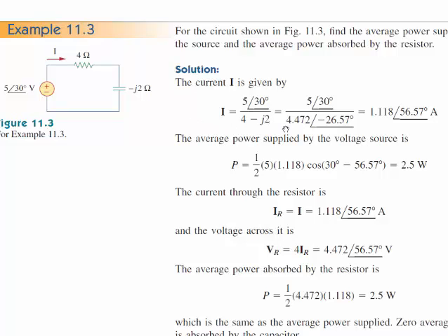But anyway, you have to analyze this circuit using all your Ohm's law, and you find out that the current is voltage divided by the total impedance. Well, the total impedance is 4 minus J2. They're in series. You just add them up. Again, now I have this mixed angular notation and complex number notation, so I have to convert it. Easier to do it in angles instead of complex numbers in this case, but for some reason I tend to gravitate towards complex numbers.